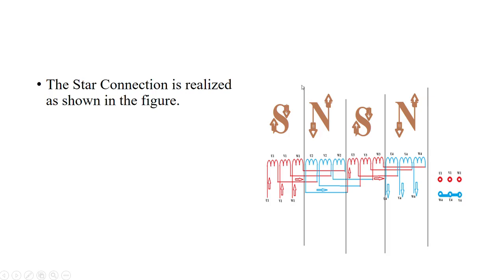If you look at, we mentioned that it's a 4 pole. This is the idea. If you read them 1, 2, 3, 1, 2, 3, 1, 2, 3, you can see that this section is a pole, this is a pole, this is a pole, this is another, the 4th pole. That's the orientation. Now, this is just a graphic to show which one is a south pole, which one is a north pole. It's supposed to alternate to aid each other.